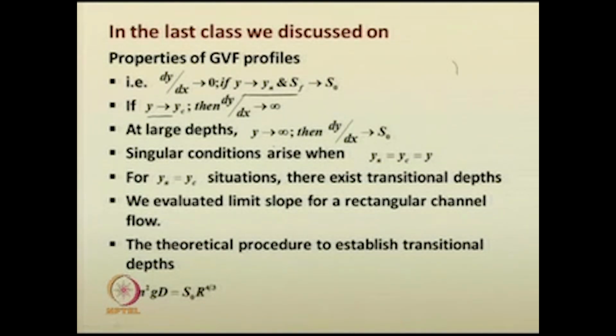You have also seen certain singular conditions arise. Singular conditions means when dy by dx takes the 0 by 0 form. A singular condition arises when the normal depth is the same as the critical depth, and this is the same as the depth of flow. We have gone through the situation where the normal depth is equal to the critical depth. In such situations, there exist transitional depths or transitional profiles.